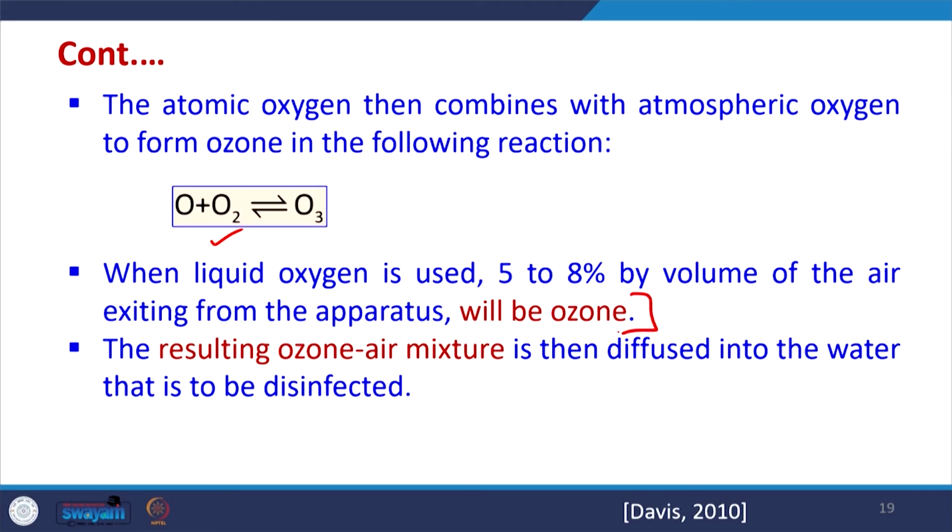So, we have to take precaution that this should not leave the system except by going into the water for treatment. The resulting ozone air mixture is then diffused into water, and we have to see that all the ozone which is generated is used only for treatment and disinfection of the water, not for any other purpose.